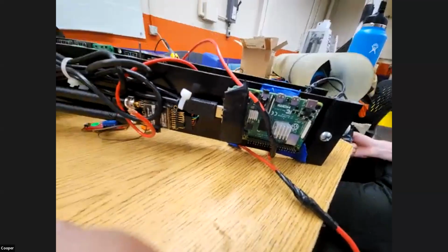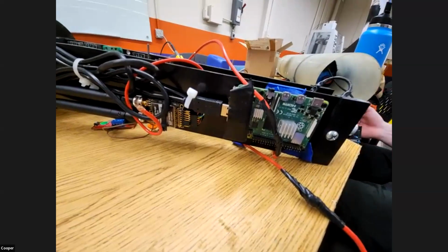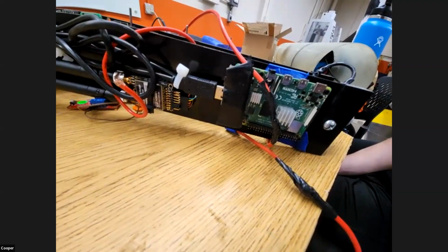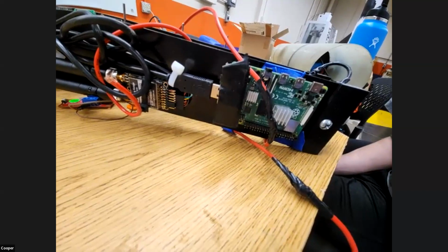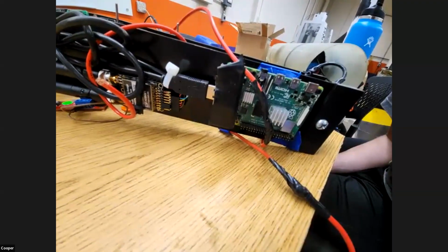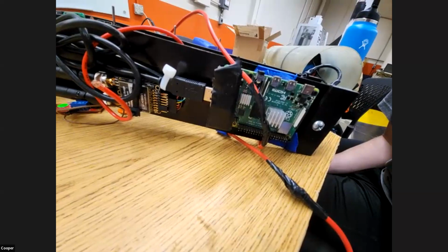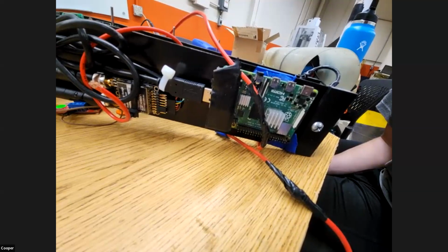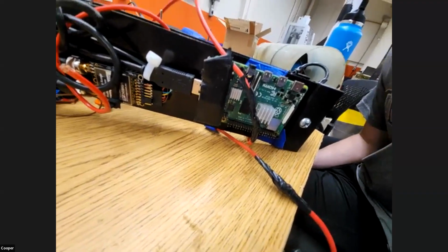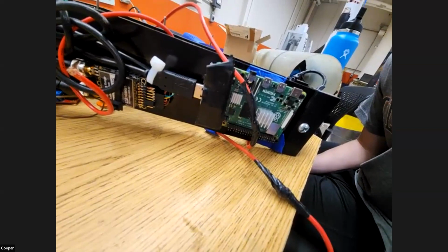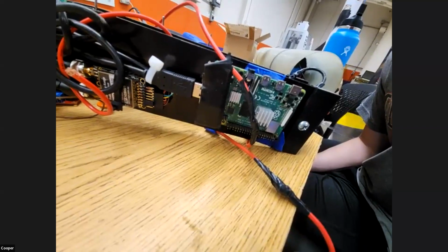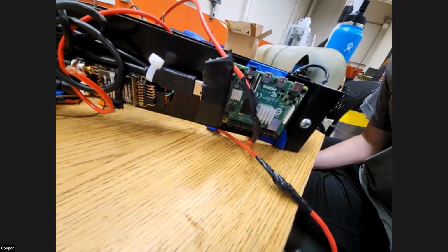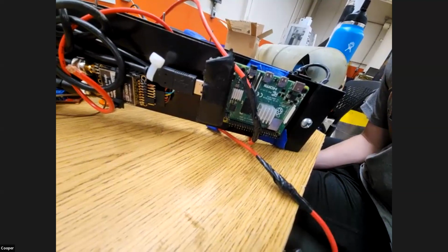All right. Connection points. So the worst thing in the universe for a Raspberry Pi is all those horrible little mini connection points. You've got USBs that are plugging in, you've got all these other things. So a shake, rattle, and roll test on your avionics sled is very important. When you get it all put together and you get all your systems working the way they're supposed to in a rocket, if you've got a shaker table or something similar to it, you need to start putting that through some pretty significant testing. You want to double check all your connections.